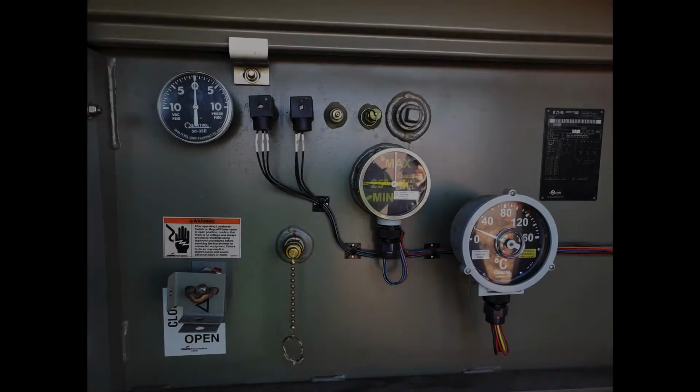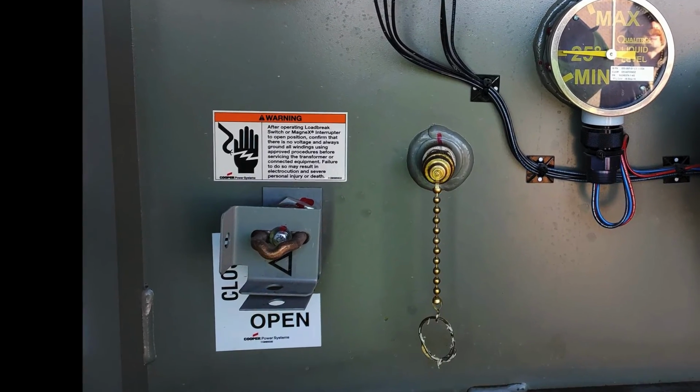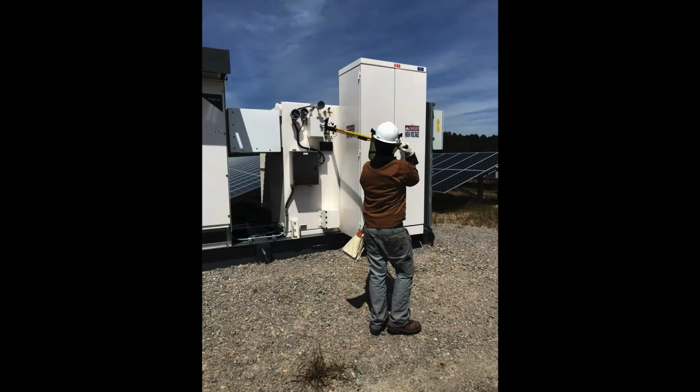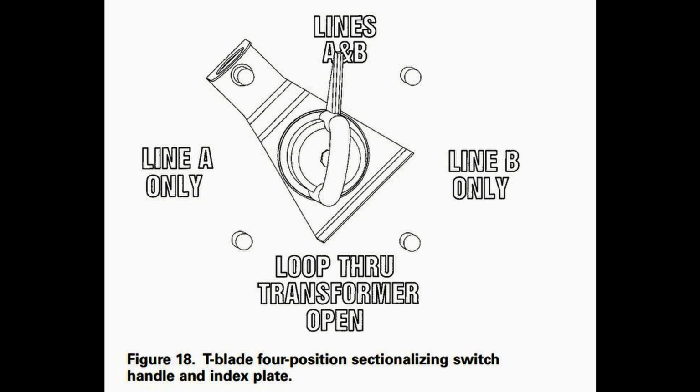This is the switch that is used to turn the transformer on or off. It does not de-energize the terminals, but it does open the circuit between the terminals and the coil of the primary side. Some disconnects only have on and off positions, but there are also variations that allow for selective switching of specific secondary circuits.